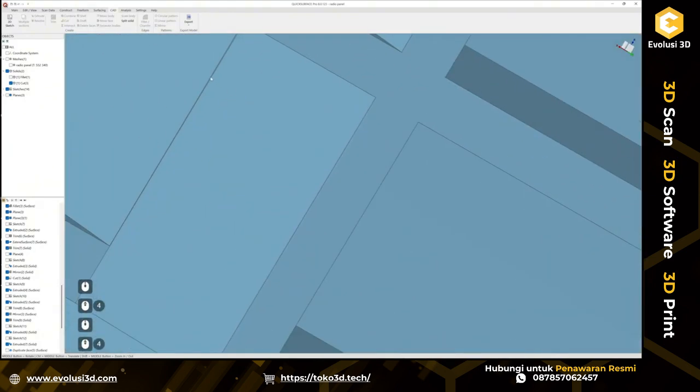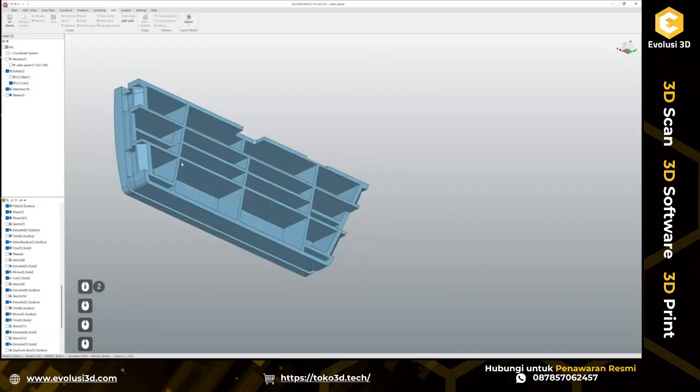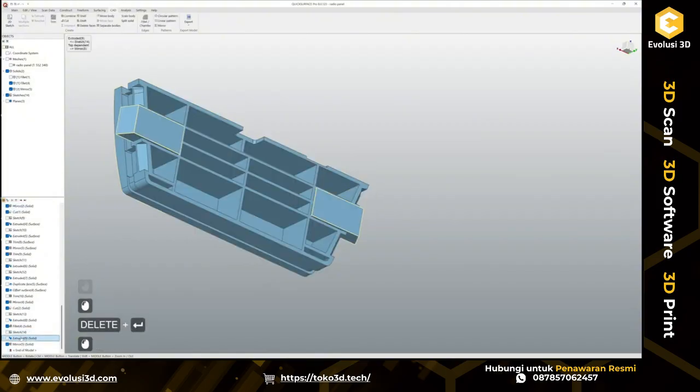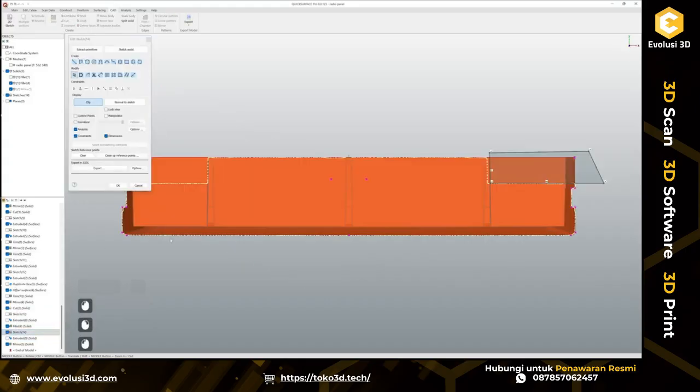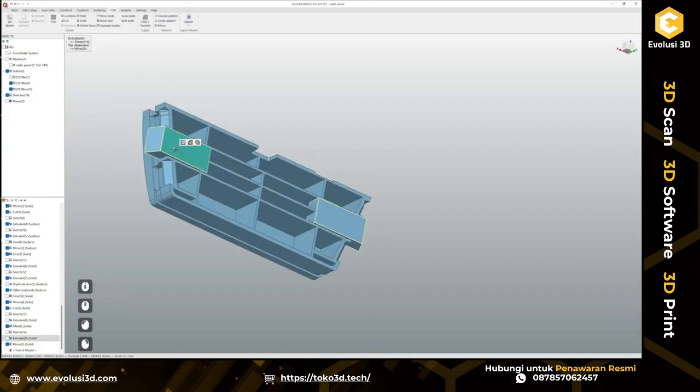Okay, so here is some flaw, just because those were not a completely vertical in sketch. Let's get back, let's get rid of this cut. Edit sketch, just pull it in like this.